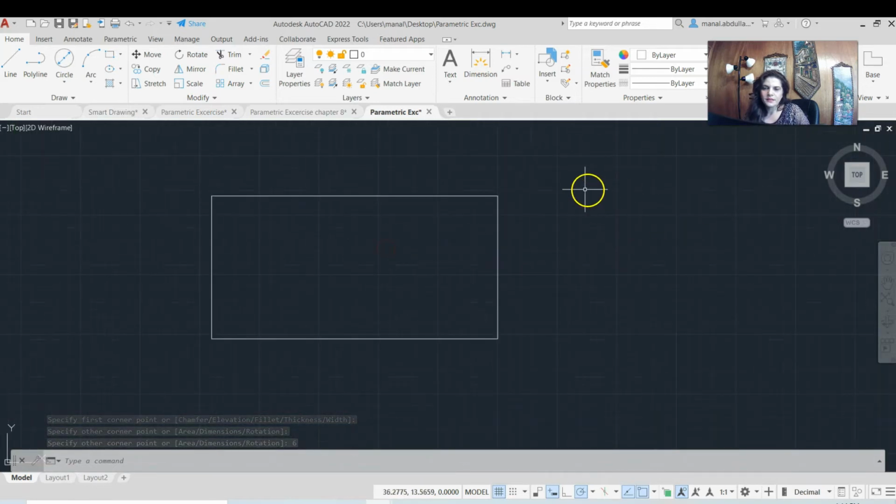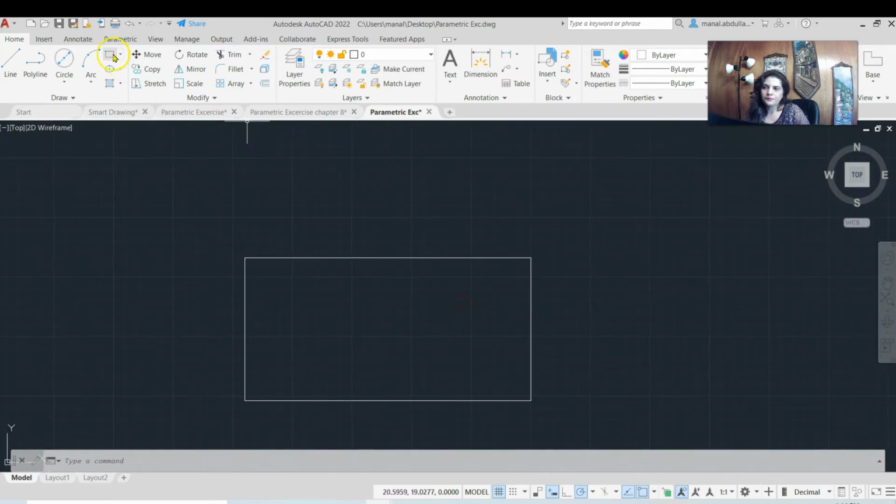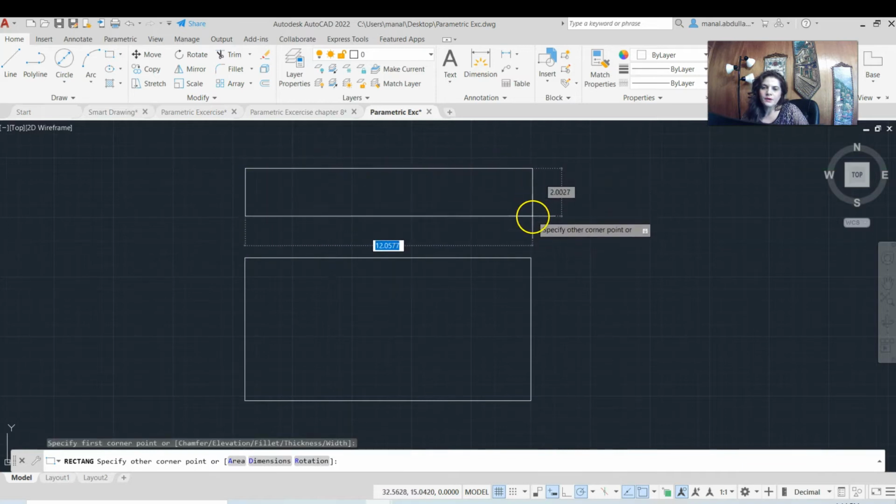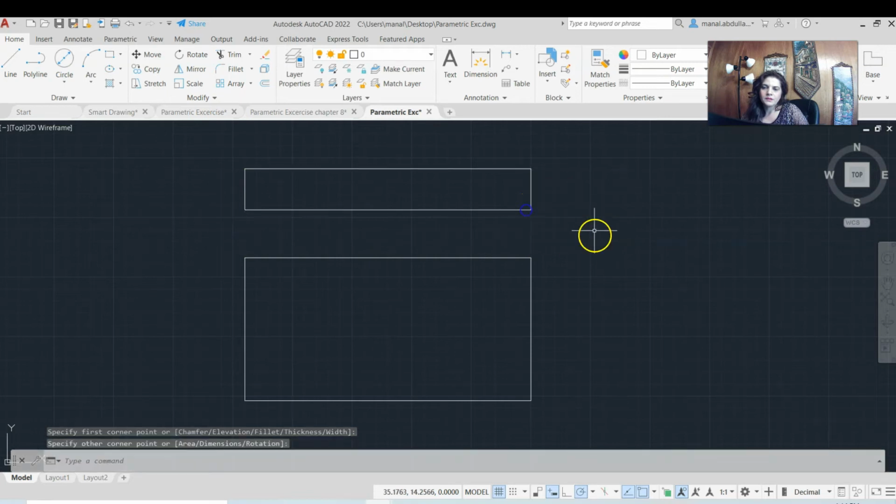Now after that, I will make another section. You can create layers as well to just put your drawing on the sections. Usually the top of you should be on a layer, and you need to create more layers for the sides of you, the elevations. More layers will be more organizing your drawing, and that is better. Now what we will do is creating the side view. Okay, just make the side view whatever that dimension, and we're gonna change it.